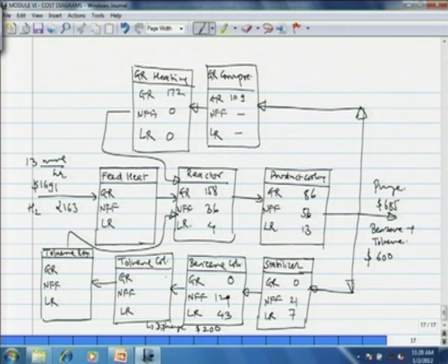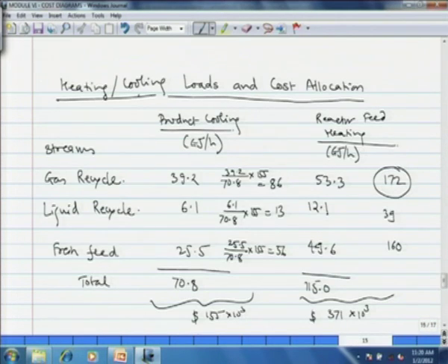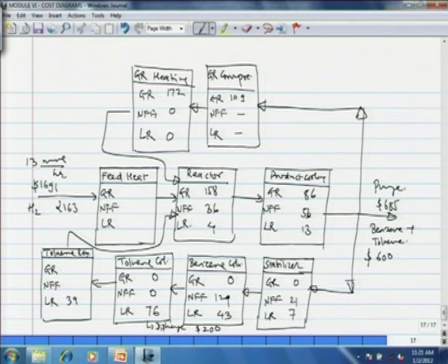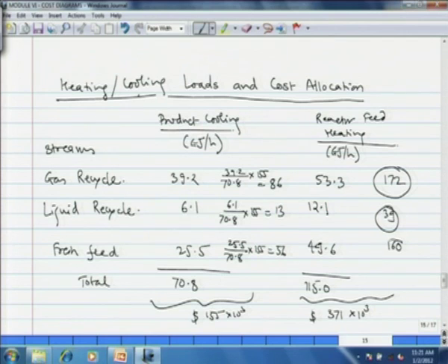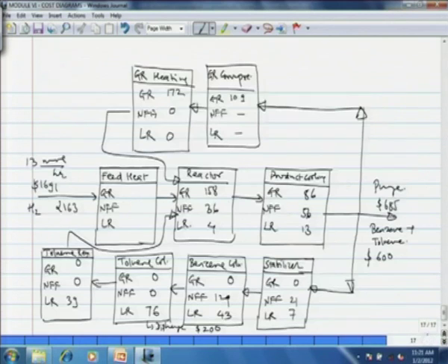Okay. Then toluene column, the total cost that we saw in the lumped cost diagram was $76,000. Entire cost is allocated to liquid recycle. Toluene recycle heating, this we have already found as $39,000. So, that we put here, liquid recycle 39, there is no gas recycle. Okay. And now finally, the fresh feed heating. The fresh feed heating we have already seen here as $160,000, reactor fresh feed heating. So, that is 160.